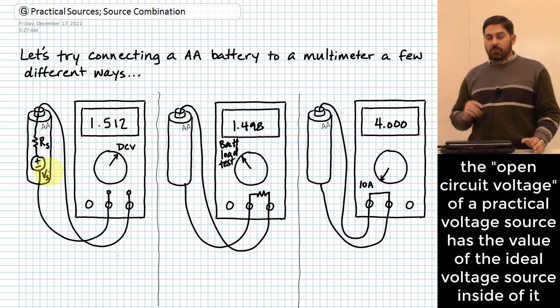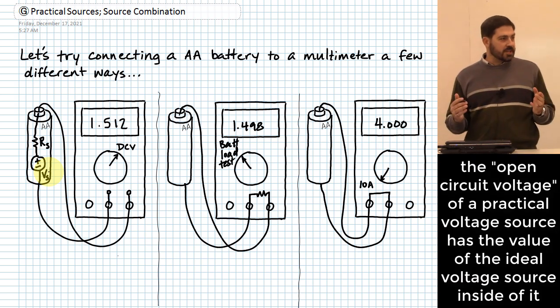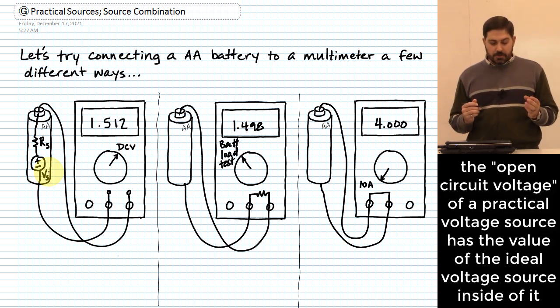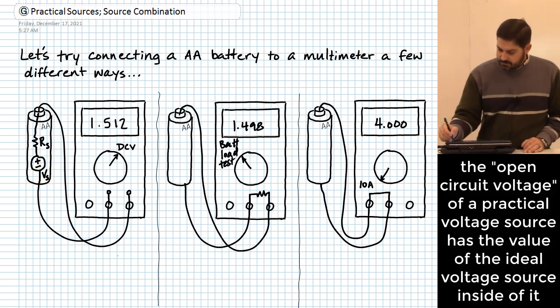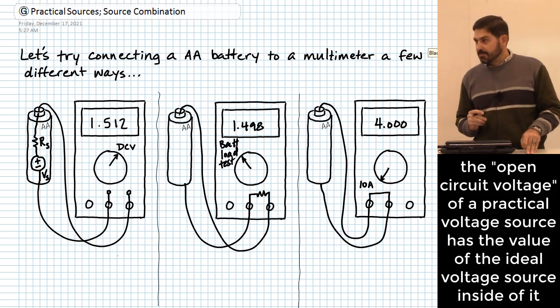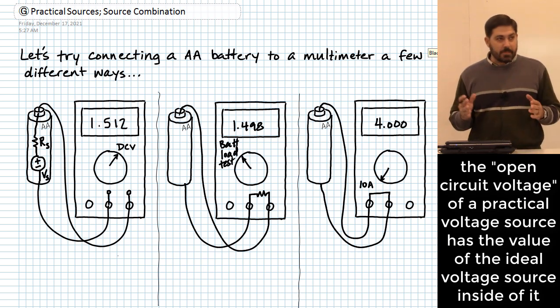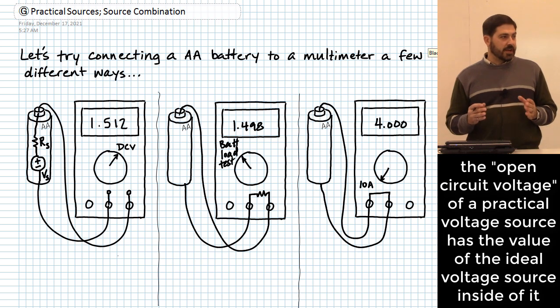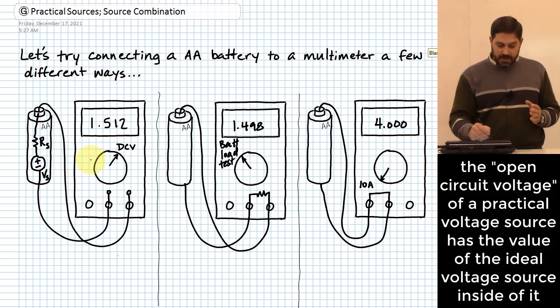If that meter really works like I represented to you that it would, then how much current flows through R sub S? Any thoughts? Is there a path for current to flow around a circuit in case number 1?